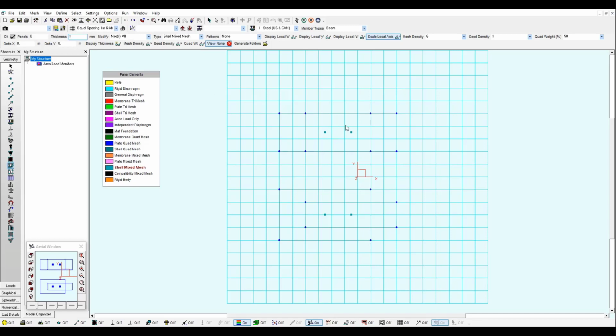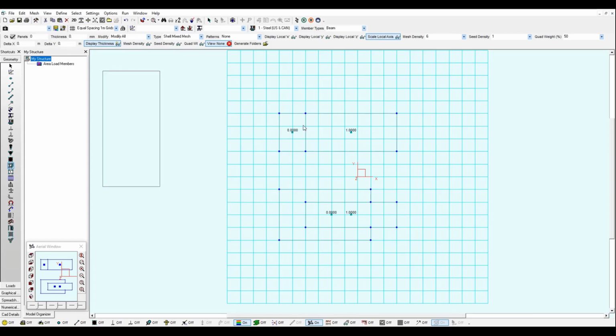And I will assign the thickness to the panels that lost against the bigger panels. In this case, both were the same dimensions, but I'm just going to assign 1 millimeter thickness, and for this panel as well. Now if I display my thickness, I can see that this panel is 0 and 1, 0 and 1. If I go over the same process, Mesh, Split Intersecting Panels, now I can see, in this case the smaller panel, in this case the panel on the right, is winning over the other panels. So the thickness has something to do with it.